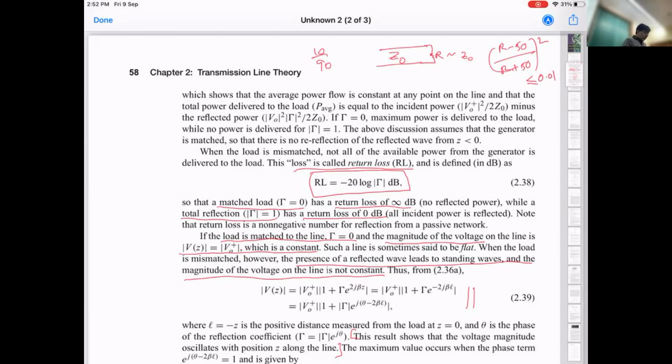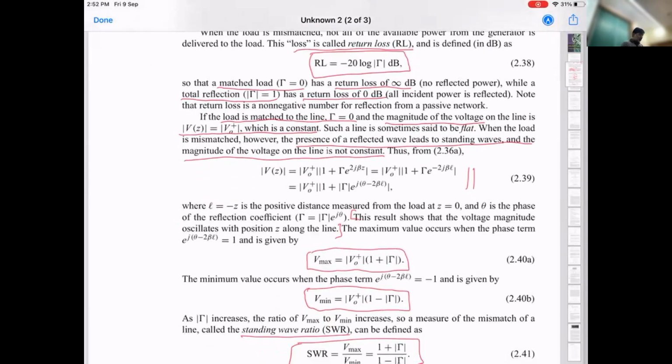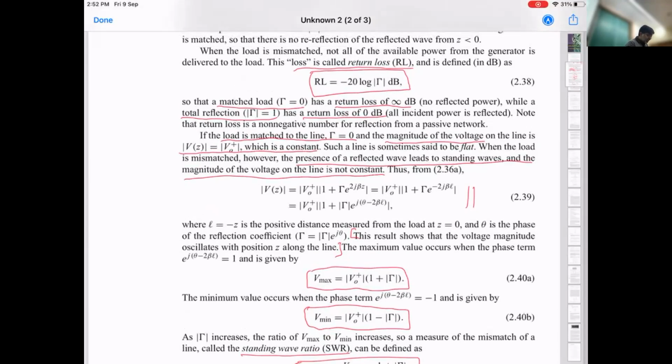Okay. So one other point here, and then we will look at what actually happens to the impedance, is another quantity which is often used to define the amount of reflection that takes place, and that is called the standing wave ratio. Now, if you look at the expression for V of z, which we had calculated, and you look at the magnitude of it along the transmission line, you will see that it's not a fixed amplitude. So remember that at the terminal z = L, it will have some amplitude, but the incoming wave has a different amplitude.